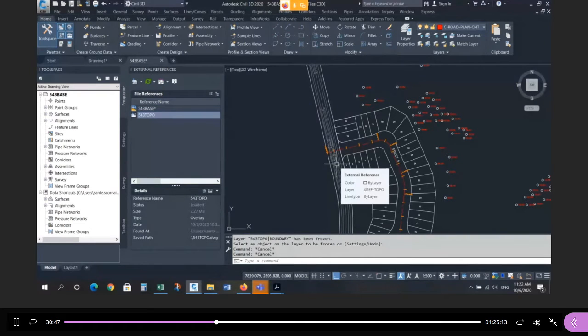If there's something that you have to show when you're printing and you don't want to see it right now because it's too much information on the screen, you could turn it off. And then it's not visible. And then before you print, make sure all the layers are on. That way everything that should show is visible and anything that should never show is already frozen. So that's why there's two layer states, right? If you never want to see it, freeze it. You don't want to delete it because you might need it for another drawing or another file or for some other function. But for the purpose of printing, freeze something you never want to see. All the layers should be on when you plot. And that's the difference between the two. That's how people use those two functions.